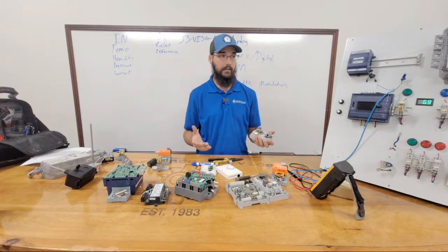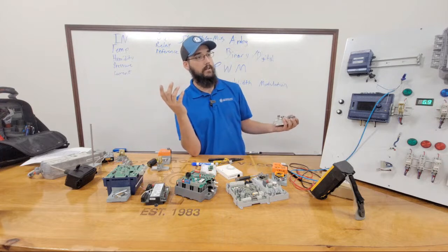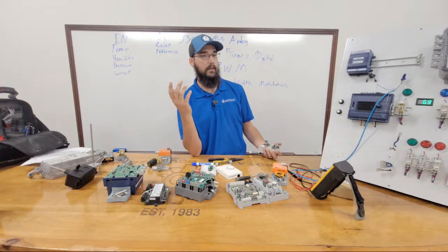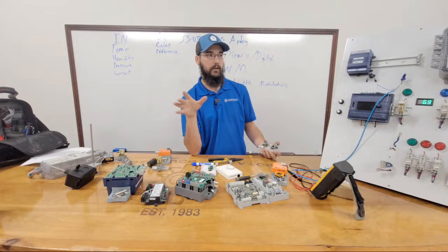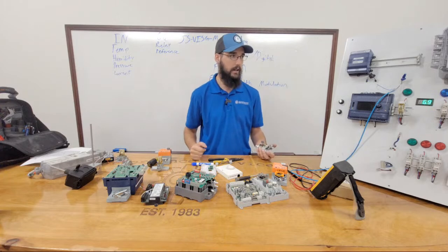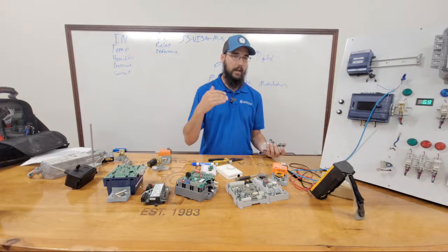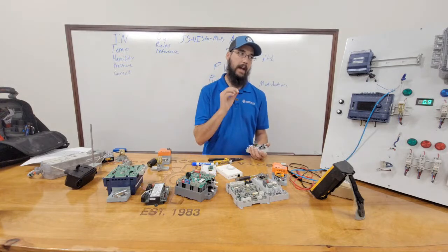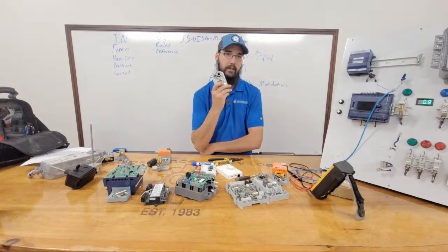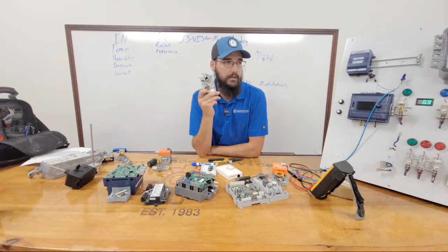So if it's a 180-second actuator, what is that, 3 minutes? 180. Yeah. If you don't give that actuator 3 minutes to completely actuate, or even if they're 90-second actuators, right? That's still a minute and a half. It's really easy to be impatient with that. So if you react too soon and that controller hadn't finished actuating this thing, you didn't accomplish anything.